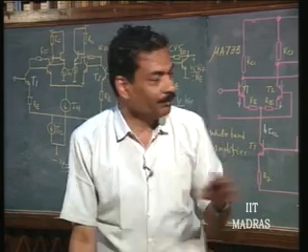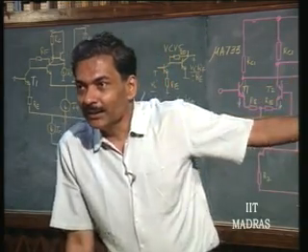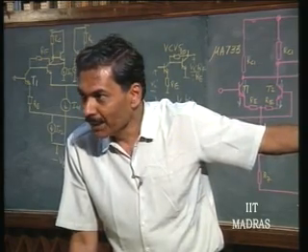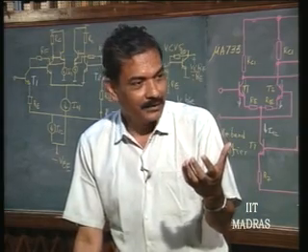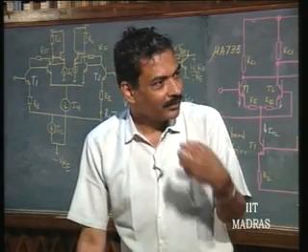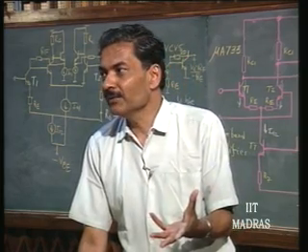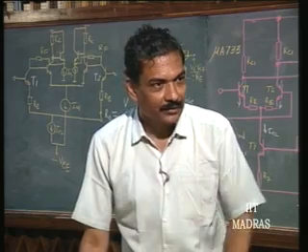Otherwise, you can simply languish in the luxury of using these low loop gain. These are all having low loop gain. If you use 2 stages, loop gain is going to be boosted up, and therefore, it is going to be more desensitized, but the price you are paying is in terms of trouble due to oscillations. Thank you.